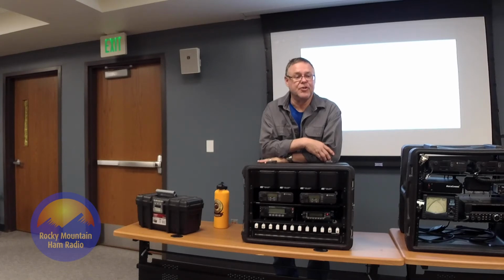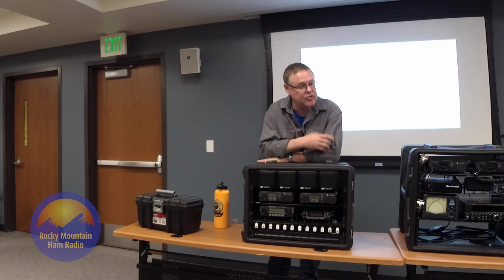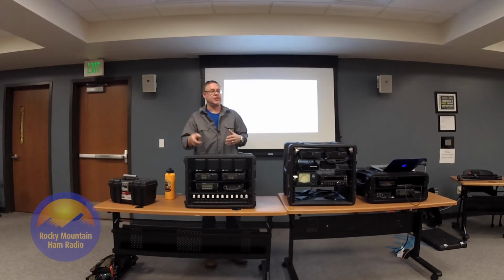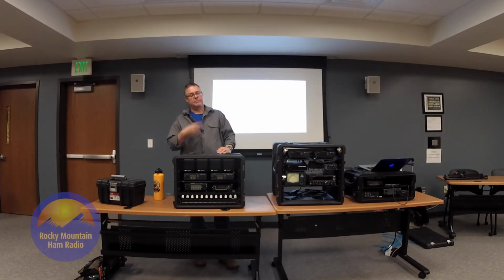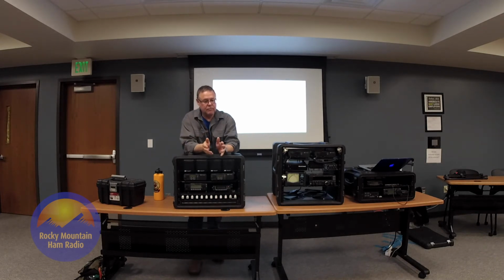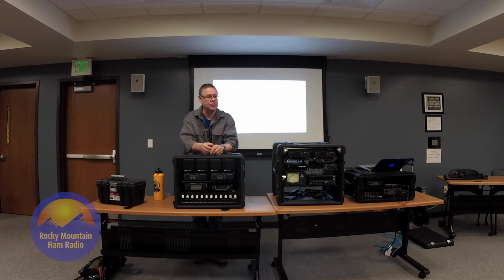If you're looking into something, at least if you can afford a generator, this Energizer I'm telling you about, and the Hondas, they're inverter generators. What that means is they don't have the engine turning a generator directly. The engine in them is turning an alternator or whatever it may be that creates 24 or 48 volts, and then they have pure sine wave or modified sine wave inverters in them, depending on how much you choose to spend.